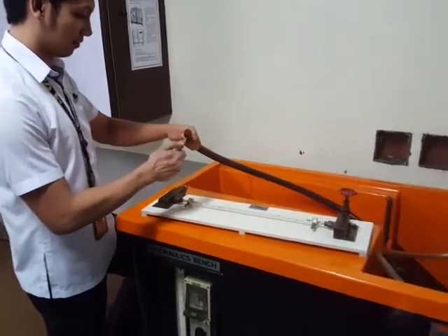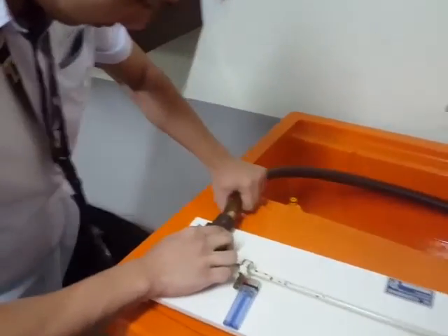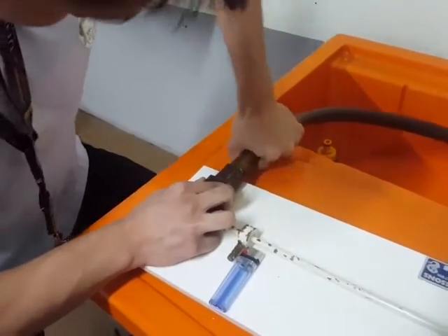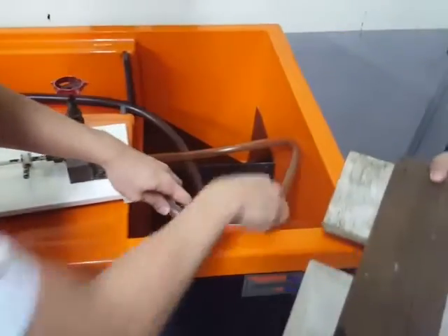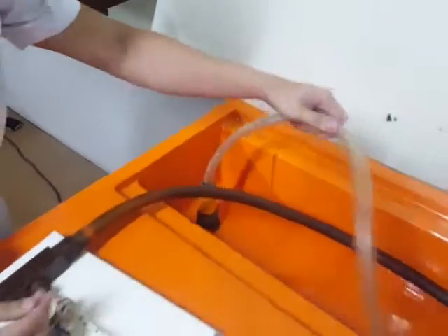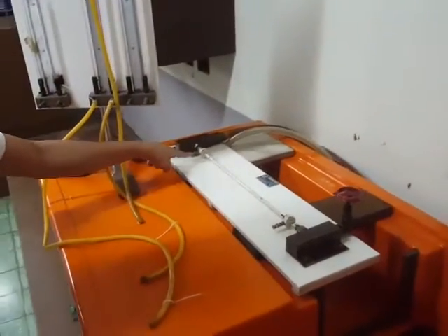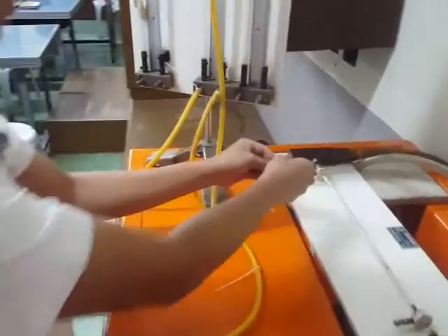Connect the pipes to the hydraulics bench by using a series of tube connectors. It is very important to connect the tubes as tightly as possible to avoid unwanted outflow. Once the hydraulics bench is connected to the straight pipe, the differential manometer is then connected to the pipe on both ends.